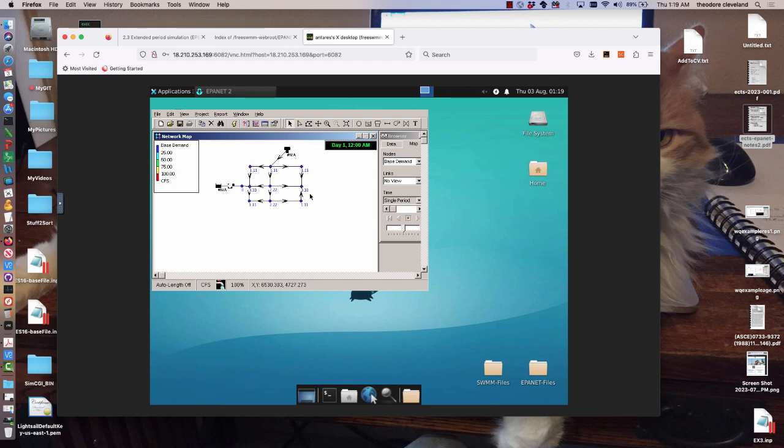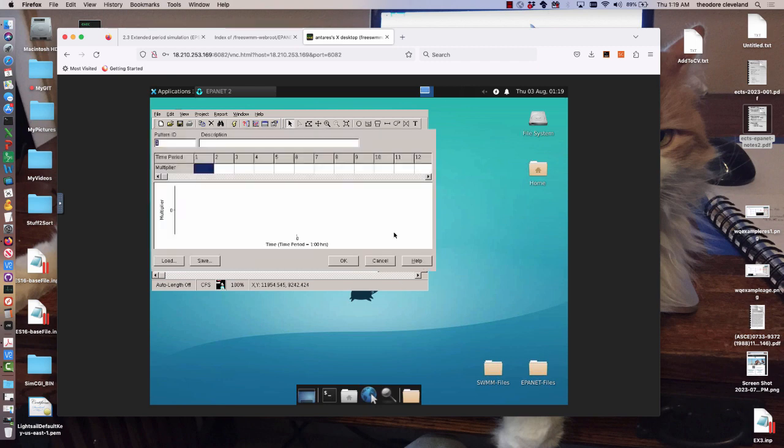No surprise there. Now let's see if there's actually any demand curves laying around in here. That's a pump curve, demand pattern. This has no demand pattern, so we're going to have to create one. And the one we wanted to create is we want to go out here to 1800 hours. I wanted to make that a multiplier of 3.